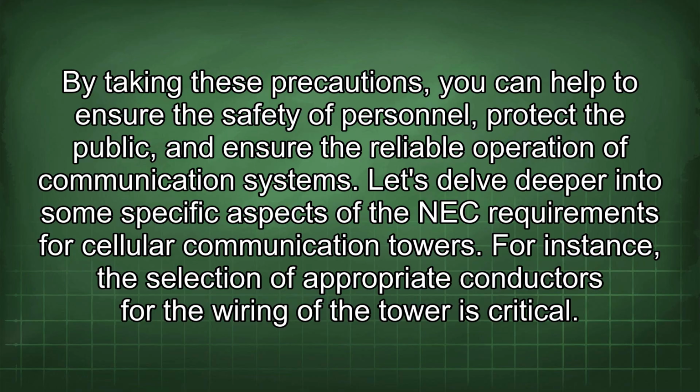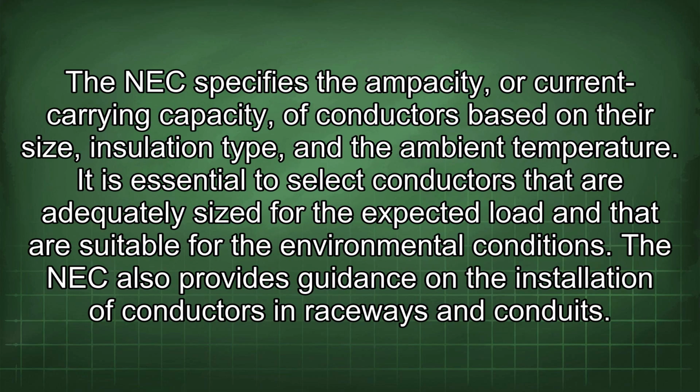For instance, the selection of appropriate conductors for the wiring of the tower is critical. The NEC specifies the ampacity, or current carrying capacity, of conductors based on their size, insulation type, and the ambient temperature. It is essential to select conductors that are adequately sized for the expected load and that are suitable for the environmental conditions.